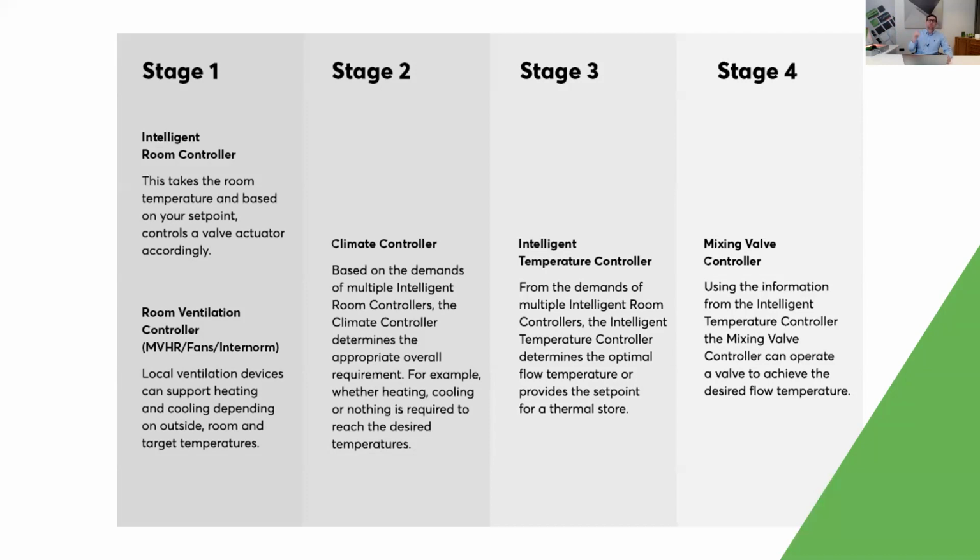And then by adjusting the flow rates, the amount of water into each of these zones, we then granularly adjust the temperature in these rooms, which means that we get a perfect balance between a really, really efficient heating or cooling system and also a really, really comfortable one to live in.